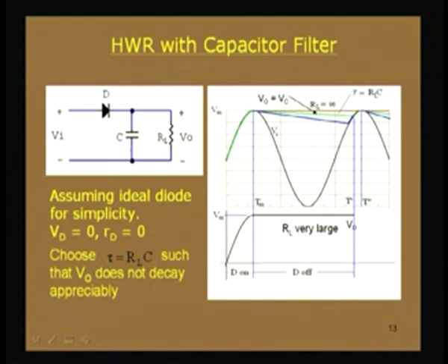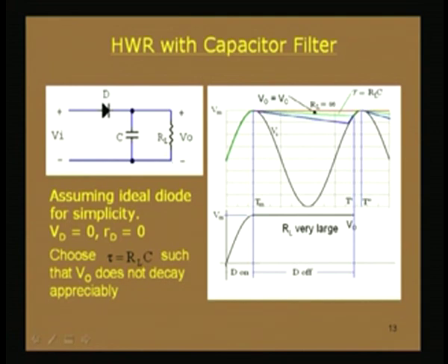The diode has 0 resistance, so the time required for charging the capacitance is almost 0, because instantly the capacitor will be charged, there will be no time lag. The capacitor will charge to the peak value of the input voltage instantly, and Vc will be the output voltage. This voltage across RL is nothing but the voltage across this capacitance.